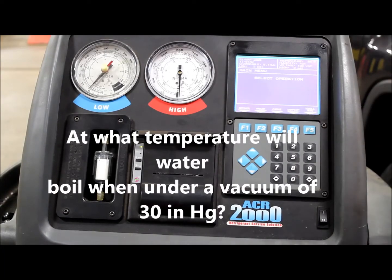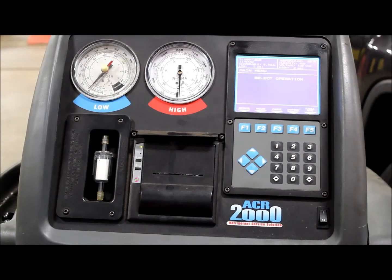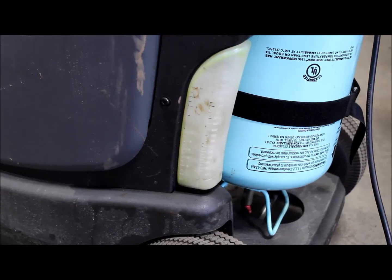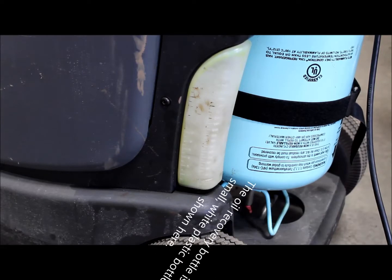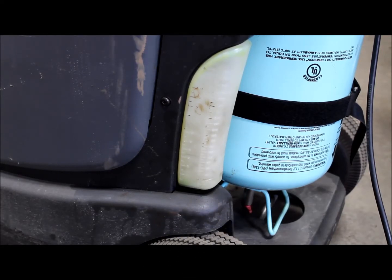I've reconnected the ACR 2000 to the vehicle. This will allow us to first recover any refrigerant remaining in the system, then apply a vacuum to it. The idea behind the vacuum is that we'll lower the boiling point of any moisture in the system down to room temperature, allow that moisture to boil out so we make sure we're not putting moisture in the system when we recharge it. Before we begin the recovery process, I've checked the oil recovery bottle to make sure there's no oil in it. If after the recovery process we see oil in this tank, then we know that we've removed oil from the system and we're going to have to add fresh oil when we recharge.